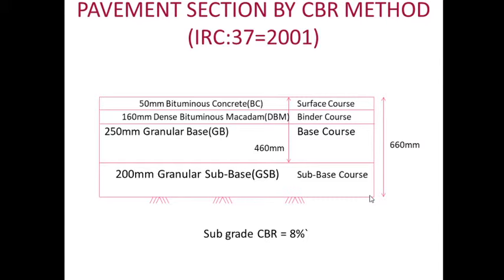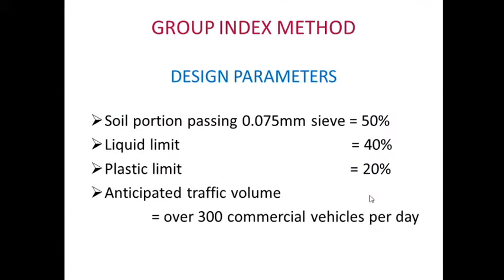Out of the 660 mm, 200 mm is granular subbase, and 250 mm is base course, granular base course, or we can go for water bound macadam or wet mix macadam. The binder course is 160 mm dense bituminous macadam, and the surface course is 50 mm bituminous concrete. Next, we have to discuss another method called the group index method.